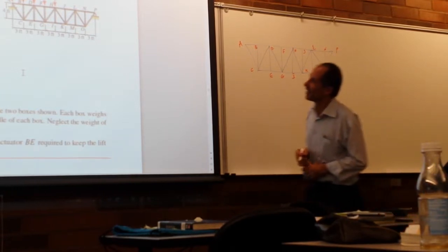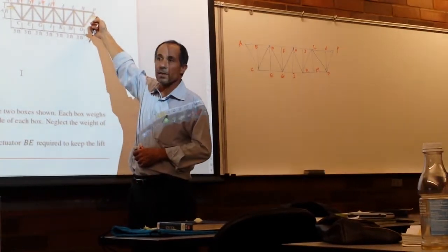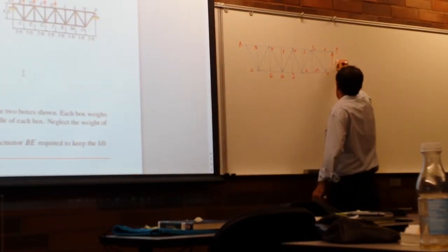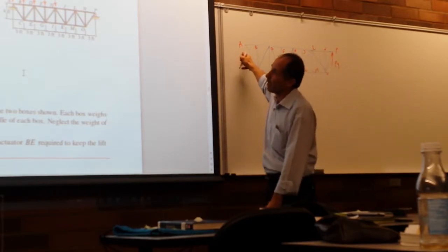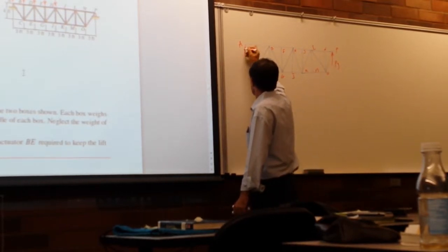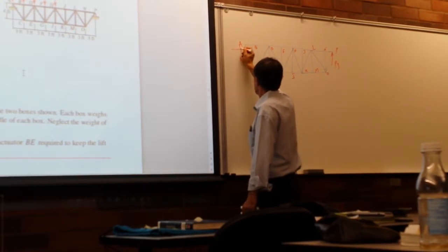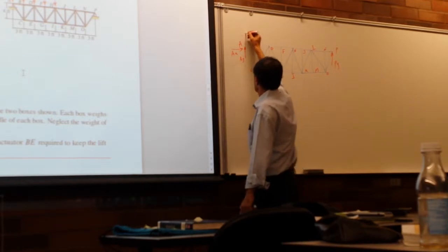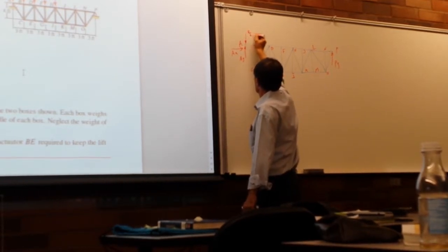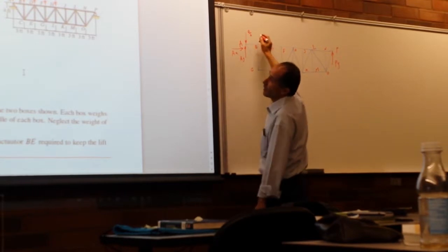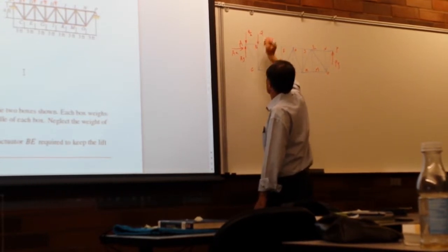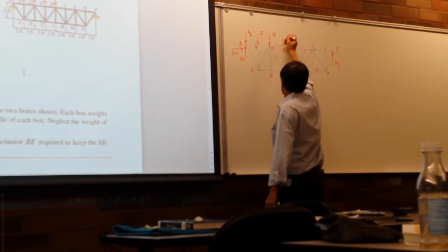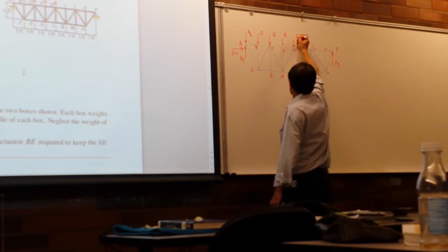So, this is a simple support, takes only one force, Py. This is A, a pin, takes two forces, Ay and Ax. Ax equals 0. This is Q over 2. This at B is Q. Q, Q, and half a Q, correct? Yes.